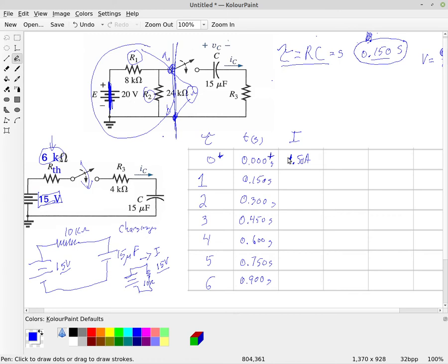Okay, I'm sorry, it would be milliamps because that was kilo ohms. So it's 1.50 milliamperes because this did have a kilo ohm down here, right? There's a K there. So it's 1.50 milliamps when you first turn that current on.